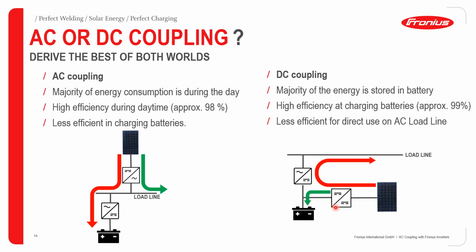But when you look at the power coming from the batteries to the loads, then here we also suffer huge losses. So I think the best battery inverters so far have an efficiency of maybe 92-93%. So therefore, out of 100, you are losing almost 7% of the available power on the DC side.